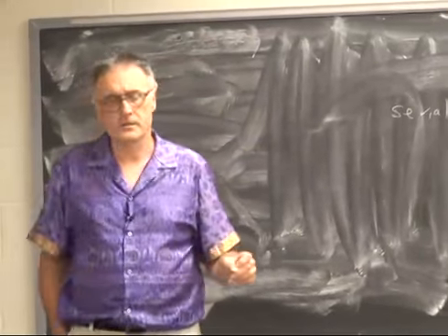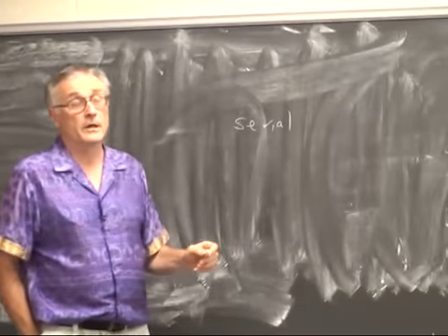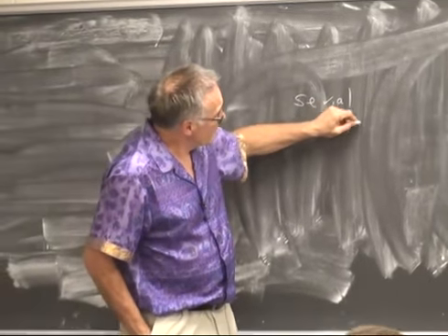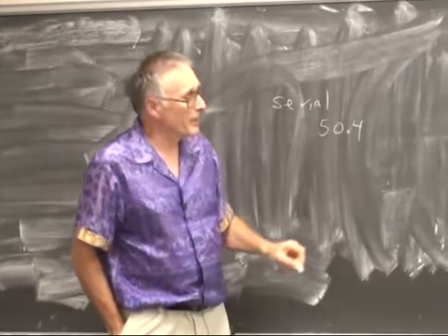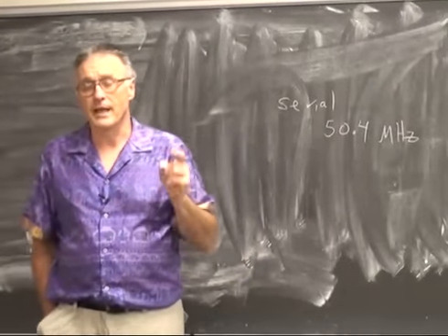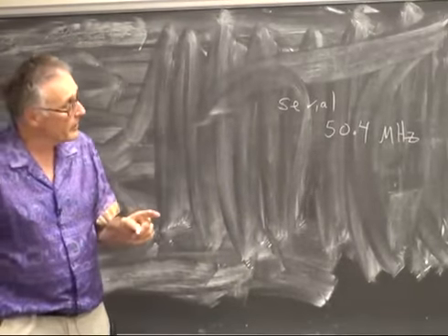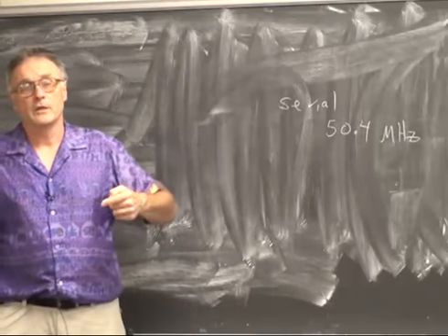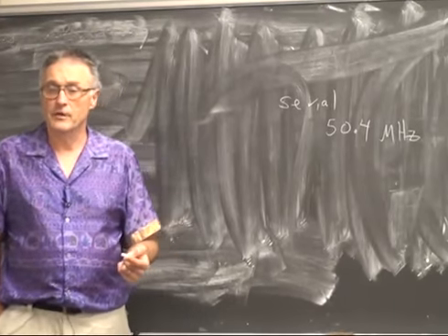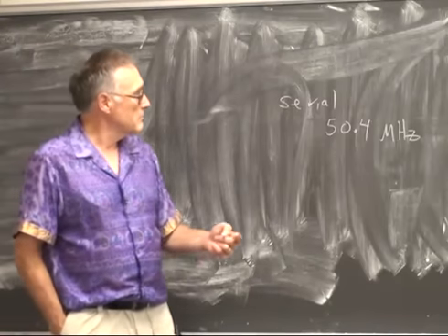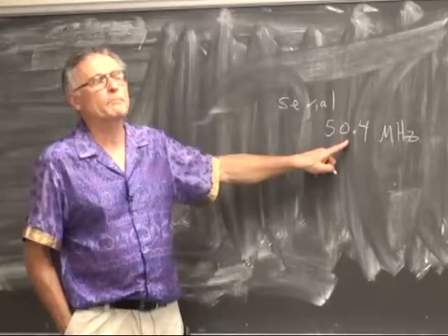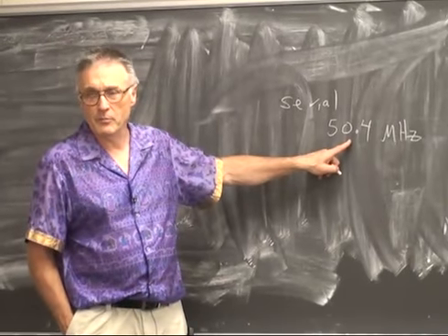The serial example from the stack machine page requires a clock frequency of 50.4 megahertz to have the correct baud rate as written. If you go into the RS-232 modules, you can change the prescaler value to be any frequency you want. Let's say 50 instead of 50.4.